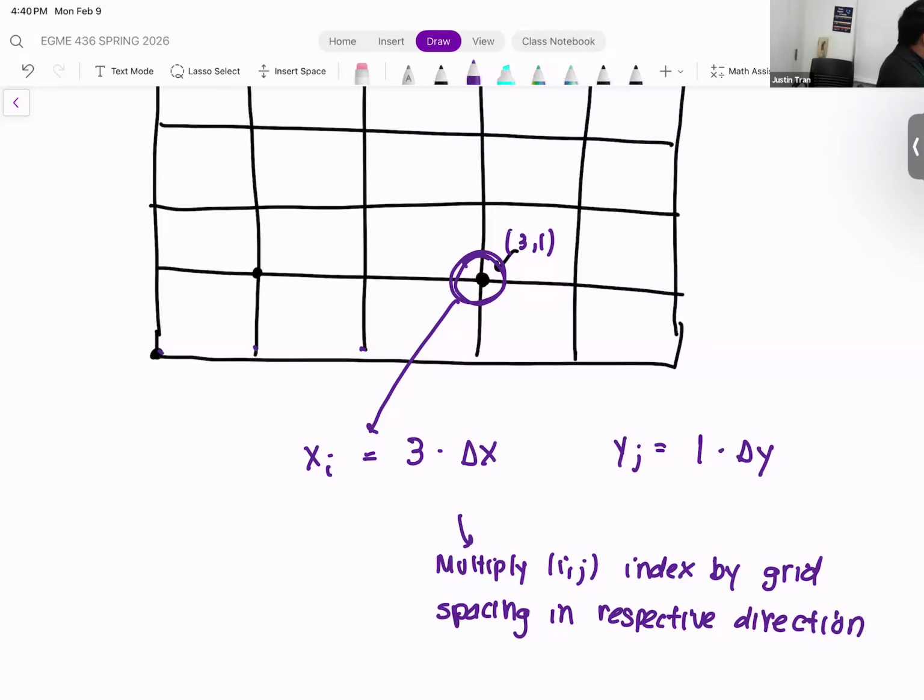I think we did actually use it in one of the examples we did last time, but I do want to be explicit with it in 2D. So when you're given an equation and there's an x floating around, there's a y floating around, usually they're going to be in the source term, but you might see them in a coefficient as well. This is how you compute it for any given node. And obviously every node has a unique physical coordinate as well.